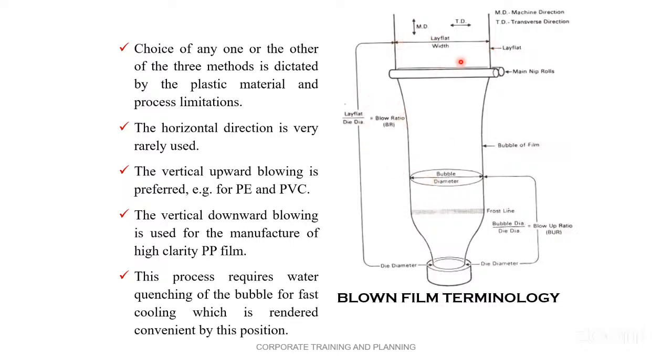See, here the film is formed. The film is poured here, friend. These are the nip rolls, right? These are the rolls. See, the film is now here. The bubble is there. It can collapse due to the wooden frame. It is not shown here. But see now here, there are nip rolls. One rubber roll and one stainless steel roll.